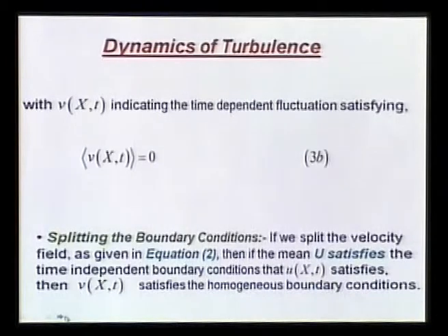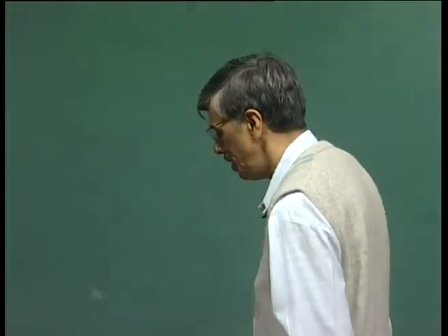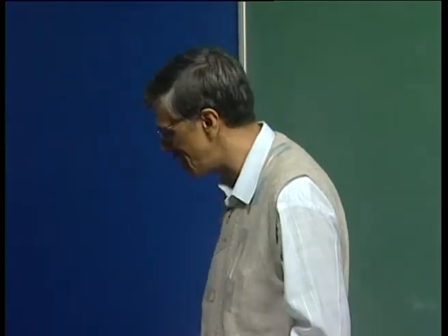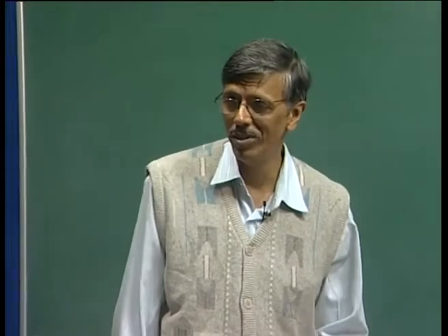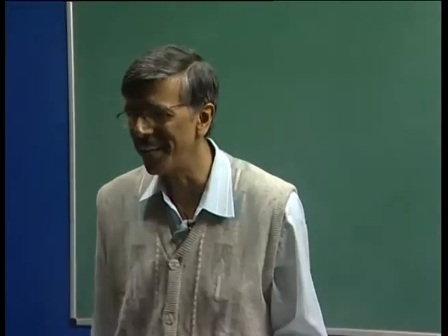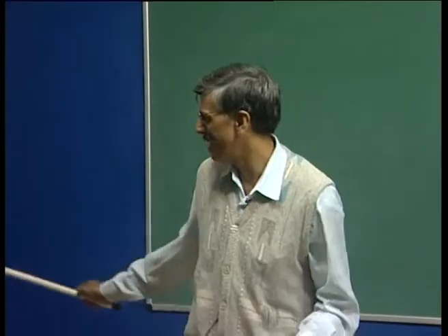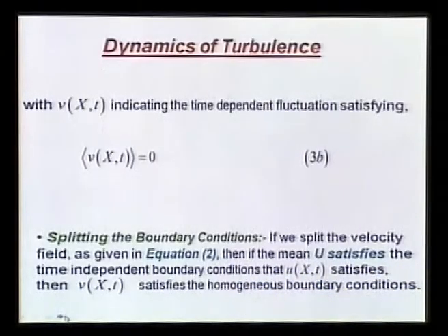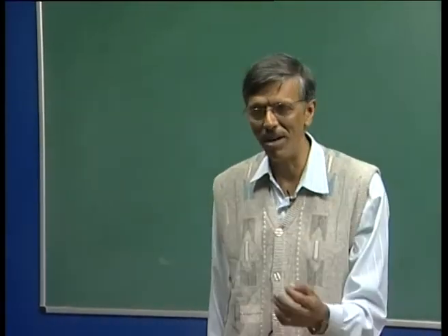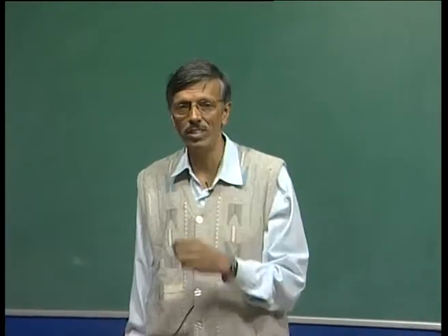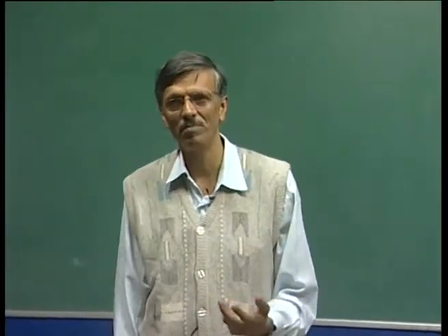Okay. So, this is the story, but there is some bit of philosophical mulling that we can indulge in at this stage. We are talking about turbulence to come out when we have not done anything to the flow, because the boundary conditions are time independent, but still somehow the flow has become time dependent. We at least have some clue where it has come about. It could be because of flow instabilities, right.